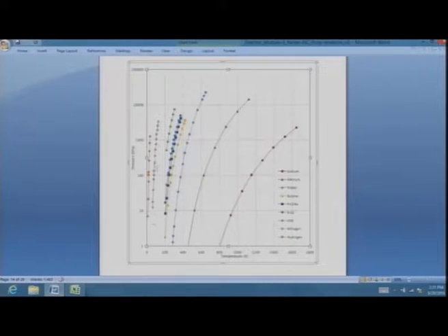So we can see that the topmost point is the critical point for each of these substances. So hydrogen goes to very high pressure, but the critical temperature is like 10 or 20 Kelvin, somewhere about that. Then you have nitrogen, which goes up to about 126 Kelvin. Then you start getting carbon dioxide, and then a lot of curves which are very, very similar to one another. They are R22, R134A, these are hydrofluorocarbons of different types. And then this one, which is butane.